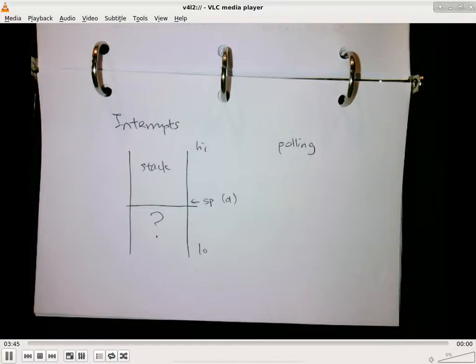So you can press multiple keys, and it will still be able to detect it. Then it moves on to the second row, puts a high voltage on the second row, but takes the voltage away from the first row, and does the same thing. So it can detect basically the entire map of all the keys and find out what key is being pressed at a particular time.